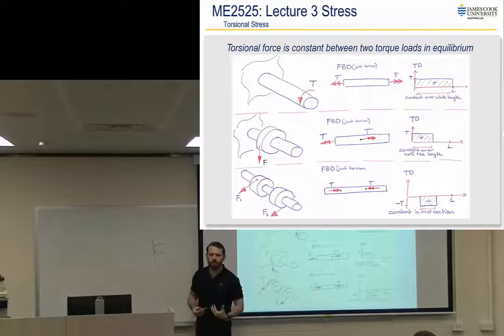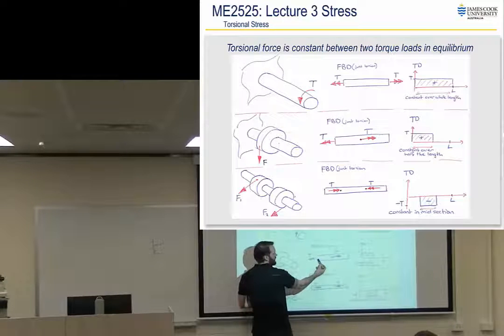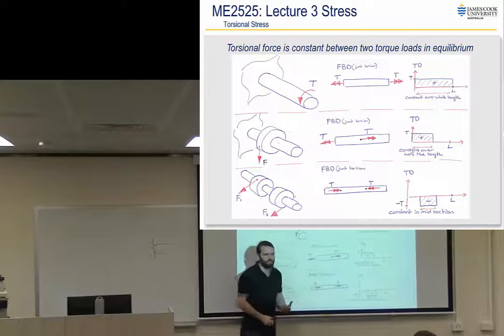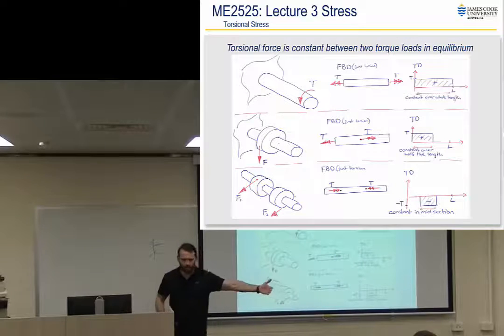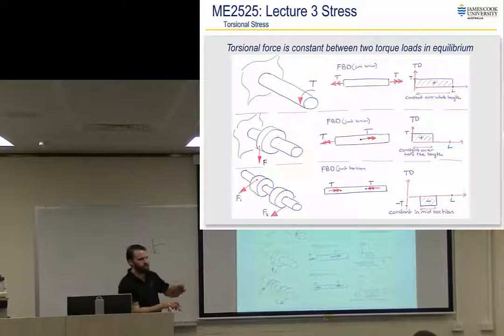Okay, so the torque diagram tells you, if you do it correctly, so take our little section there, we've got positive torque that way until we get to that point, and if I took a section just to the right of that, my sum of the torques is this one that way, and nothing left. So obviously it goes to 0 to the right-hand side of that bar. So on the torque diagram, we indicate that as 0.